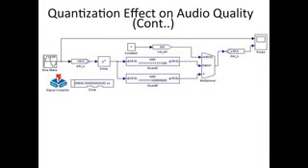In this experiment, we will create a DSP Builder model to quantize the input audio signal and then output the signal to the DAC. The signal will be quantized with different number of bits. We use the switches on the DE2 board to select the quantized signal for playback and observe the quantization effect on the signals. This is the complete design done by using Simulink.